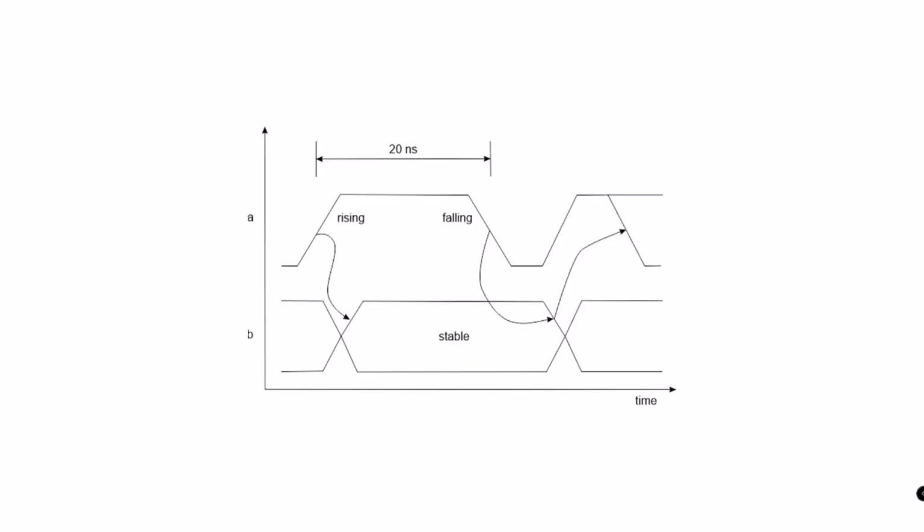A timing diagram like this one can describe the relationships between signals over time. A control signal can be at a particular value, 0 or 1. The 2 parallel lines indicate a stable value that may be either 0 or 1. A changing value is a transition from one known state to another. Rising signals change to 1, while falling signals change to 0. An edge is a rising or falling value.